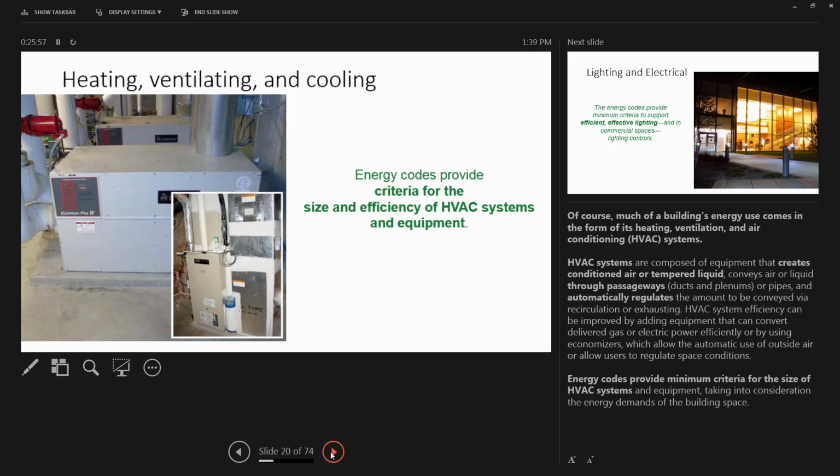Before you can get a building permit, we're going to do REScheck calculations, you have to supply the basic wall systems, all your building materials, and minimum energy performances that your building's going to meet. And we're going to spend a whole day on REScheck, and you're going to do your own calculations for some simple houses. But you can't get a building permit now with the current IECC codes without demonstrating a model of performance for the building you're going to build. You can't just say, well, I'm going to use this much insulation. You have to prove that it's going to meet that.